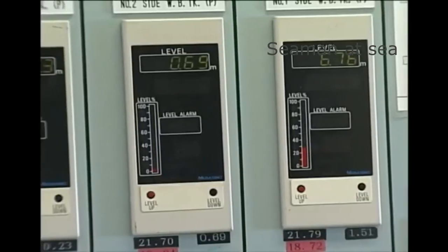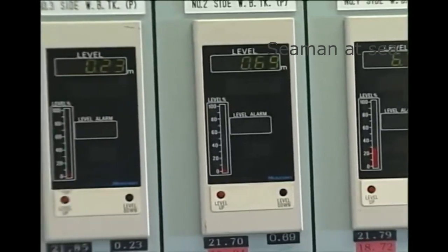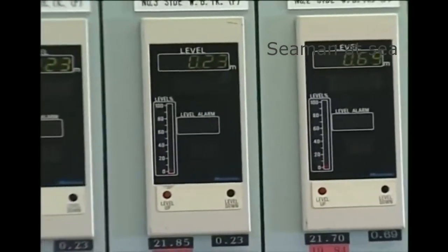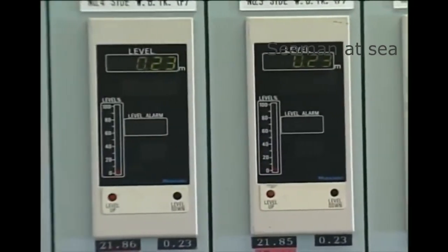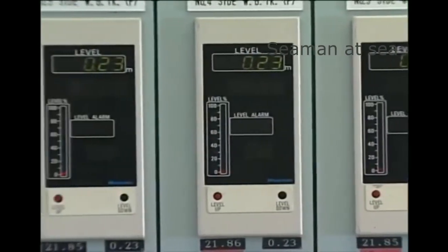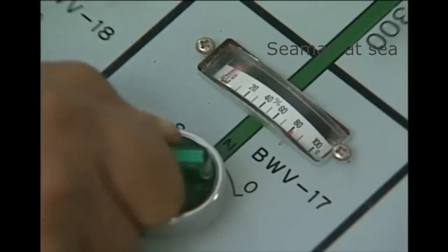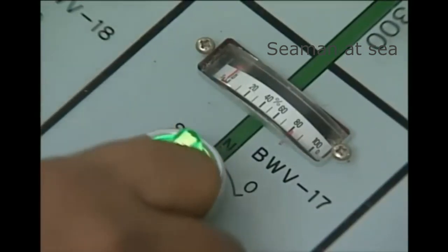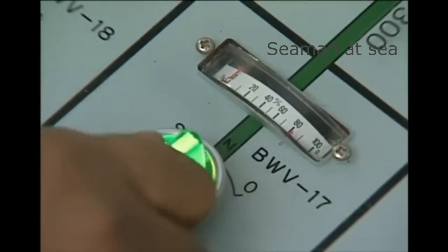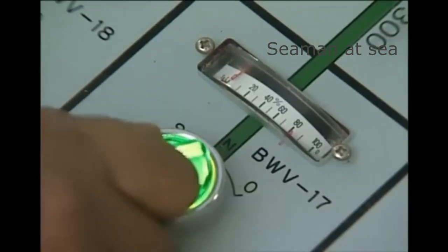To the extent possible, conduct ballast water filling into an empty main ballast pipe, either via an opening control valve or from the lower pressure tank. When the main pipe internal pressure is negative, inch open the pipe slightly and observe the state of things for a while, then fill ballast water slowly.